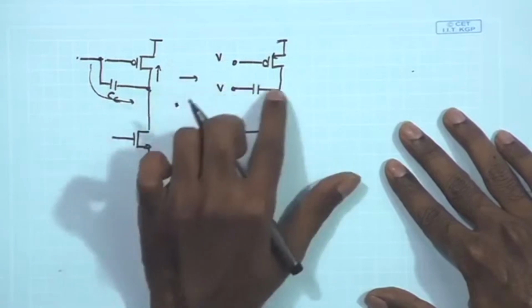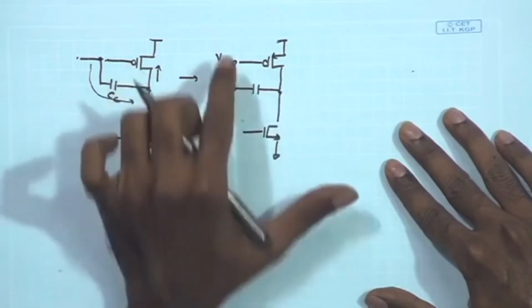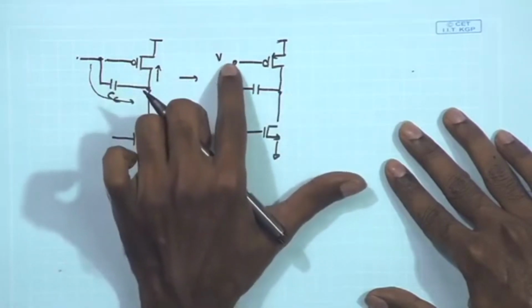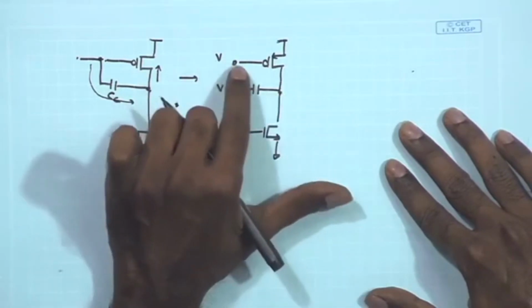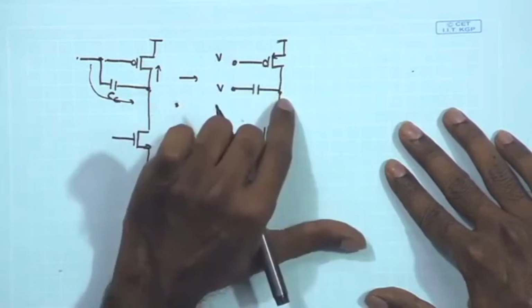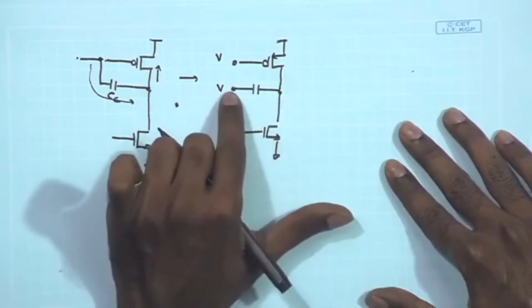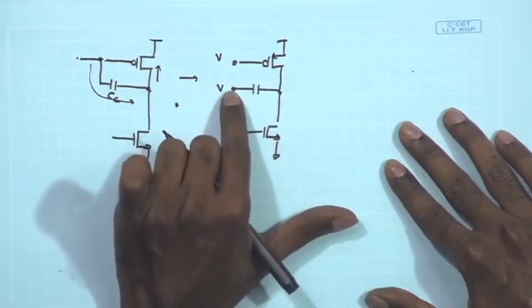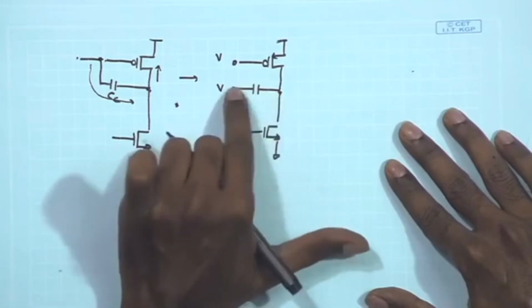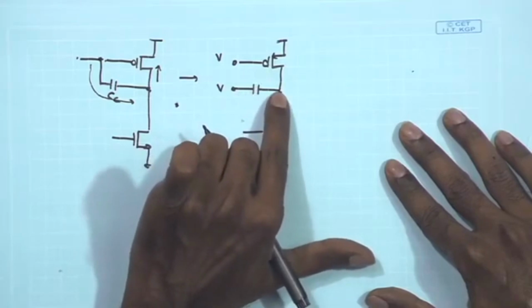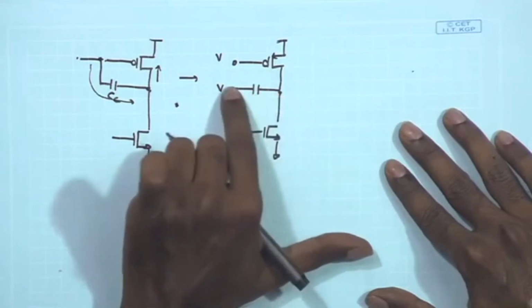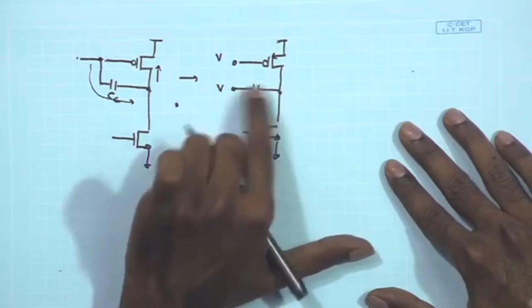We can find the overall output voltage as a superposition of these two signals. One comes from the input of the MOSFET to the output, and you have an inverting gain. If I take the effect of V applied at the gate of the MOSFET on the output, you have an inverting gain. Whereas, if I take the effect of this particular V on the output, you have some voltage division provided by this capacitor and the overall impedance, which can be relatively in phase with the applied signal.